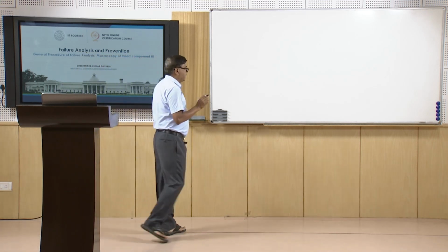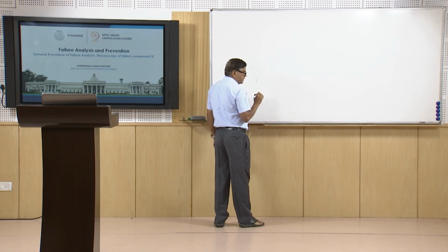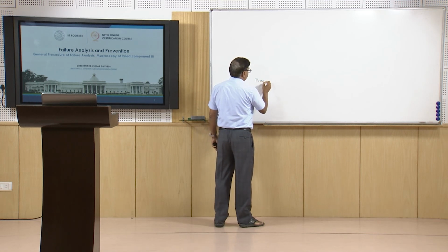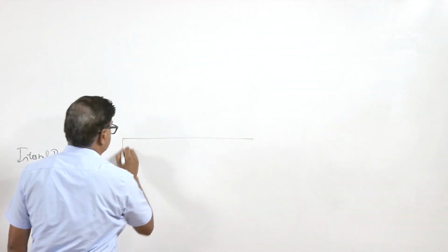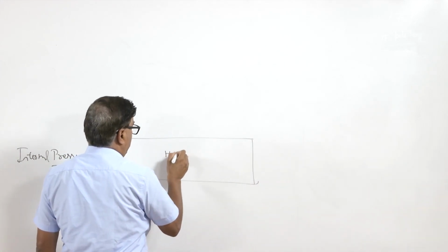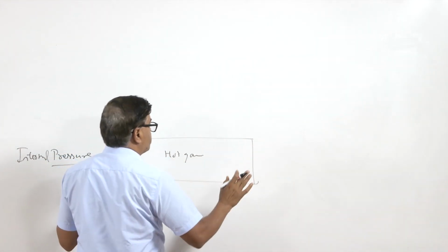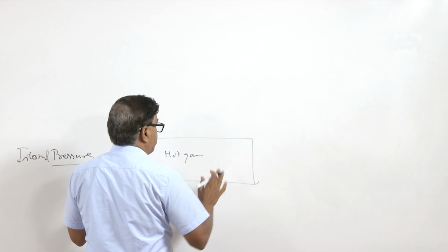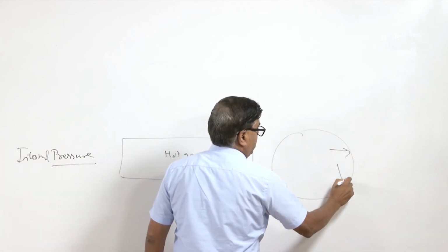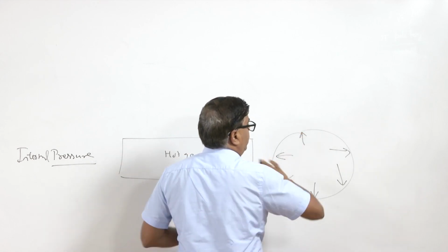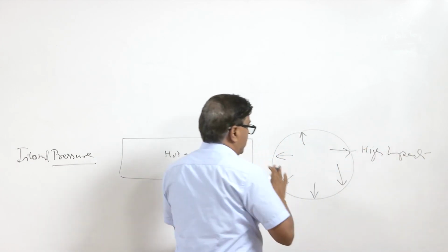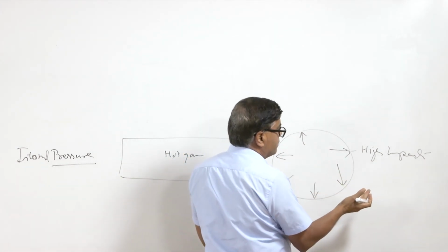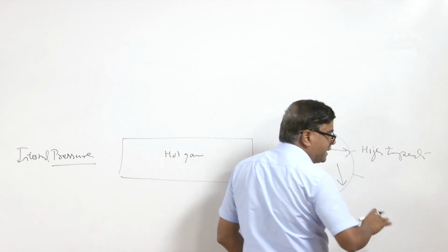Another type of fracture which occurs at a high temperature, especially in components or systems which are subjected to internal pressure and exposed to high temperature, is seen in boiler tubes, with hot gases under pressure being passed through the tubes. At a high temperature, continuous internal pressure applies force on the wall of the tube, and the high temperature leads to a continuous change in the wall thickness, maybe localized also, and this high temperature actually degrades the material properties.